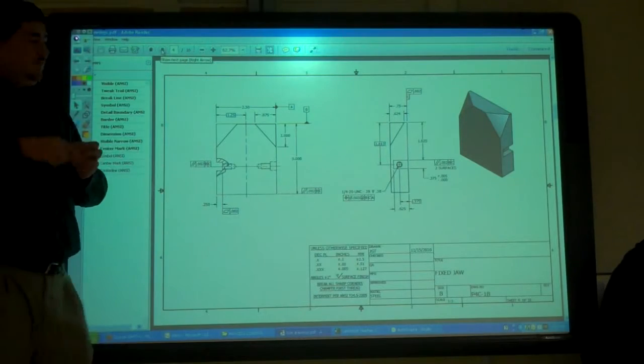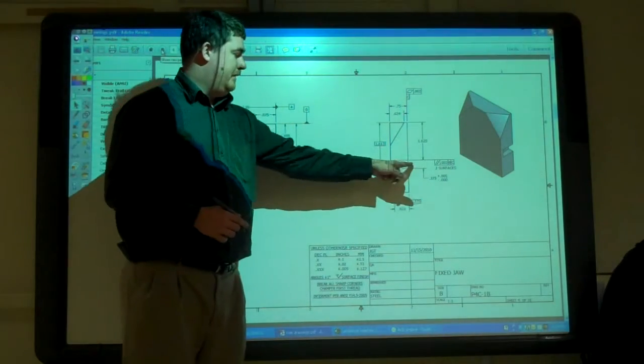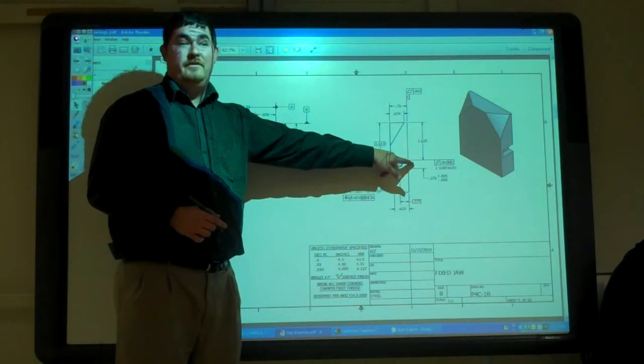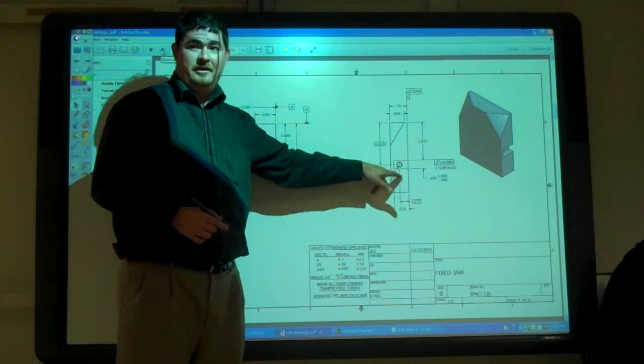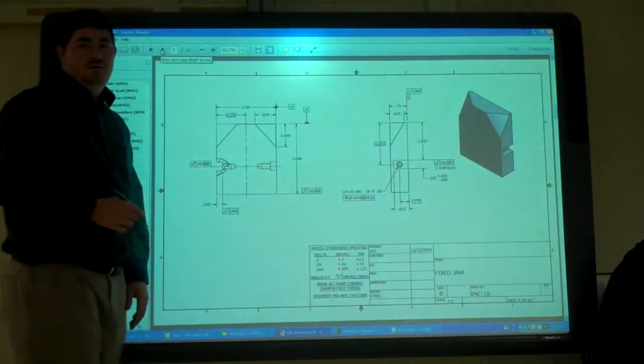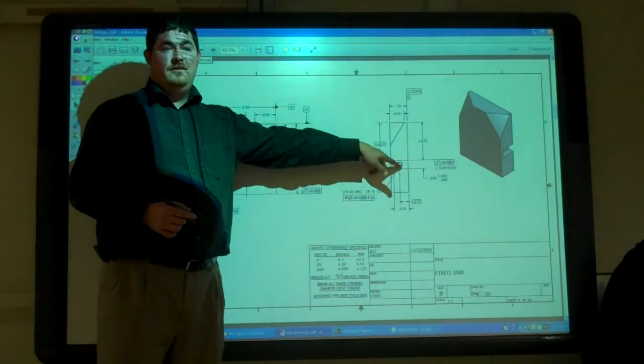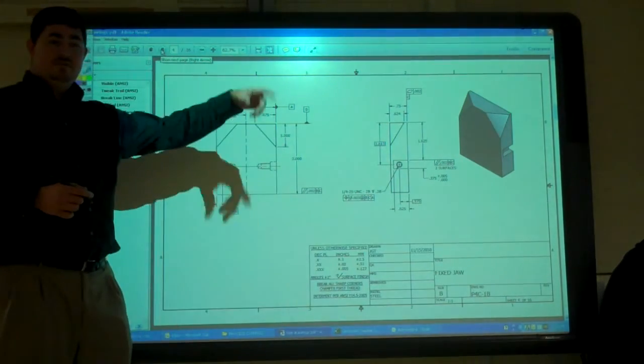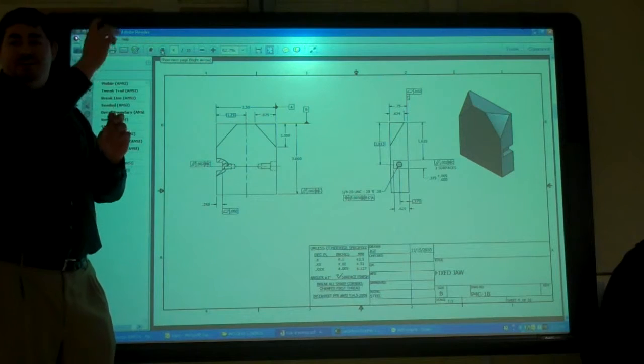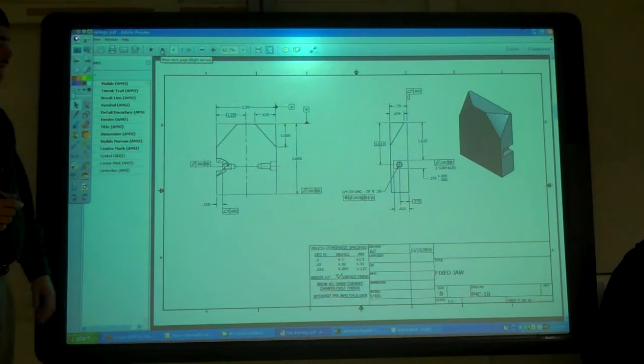And then that way they can come in with an end mill that's maybe 1/8 of an inch or 1/4 of an inch. They can do a pass there, come around another pass. So if they put a 1/4 inch in the mill, that'd be a 1/16 of an inch radius there, right? Or 1/8 of an inch radius. So that'd give them a little radius, make it a lot easier to machine.